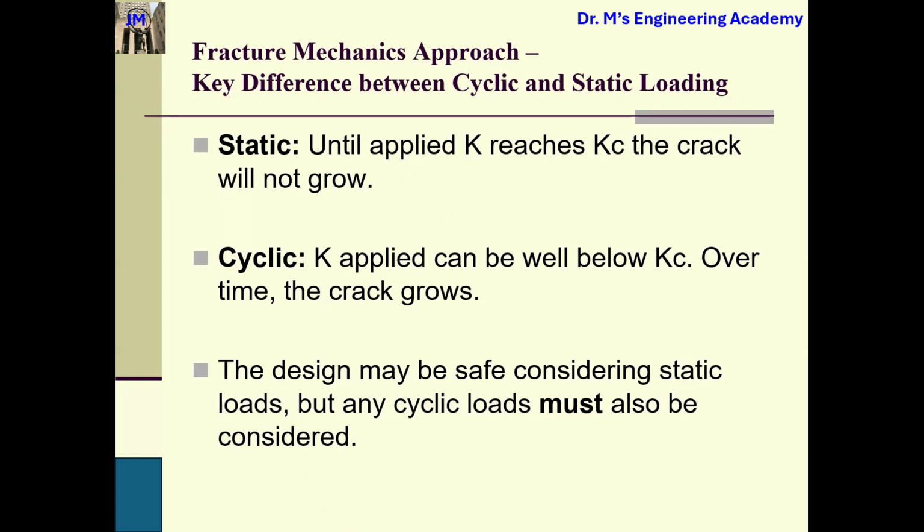However, for cyclic loading, it is another story. Okay, you can see the K. So this actual K can be very, very low compared to KC. However, the number of cycles is involved, so this is very, very dangerous.